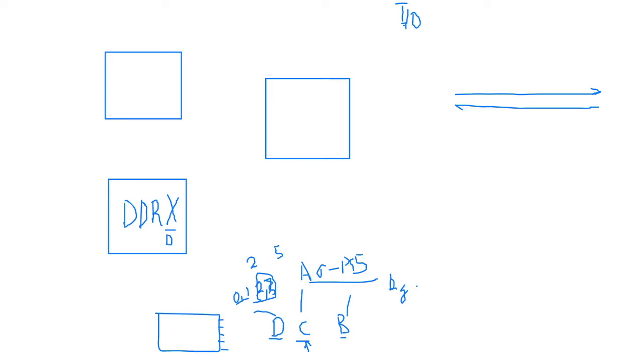Now, in here, we get to decide whether a particular pin is an input or an output. An easy way to remember, I would expect 1 to be the input because 1 looks like an I, and I expect 0 to be the output. That's my expectation. Don't confuse yourself at this stage, right? But remember, as far as AVR architecture is concerned, it is the inverse.